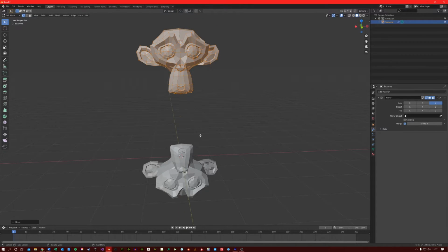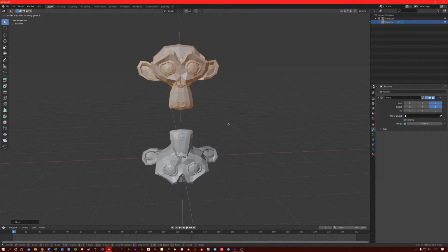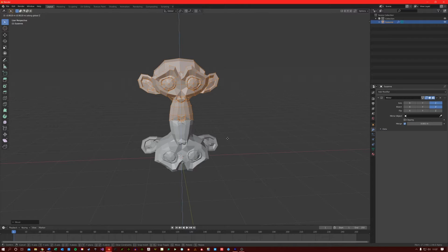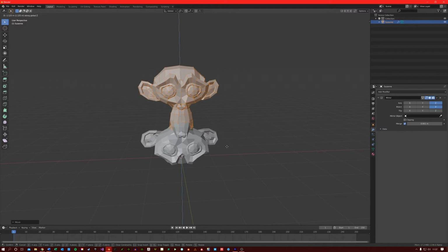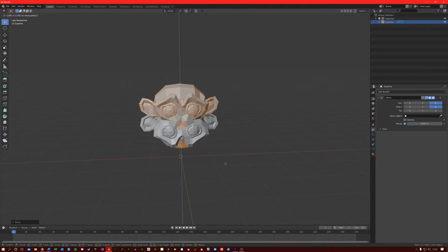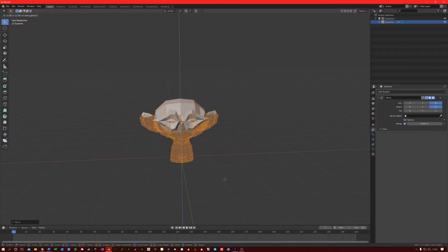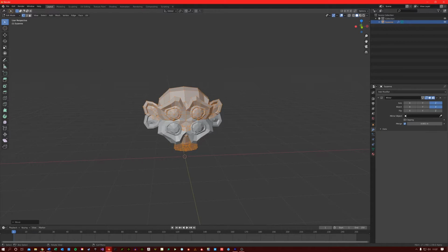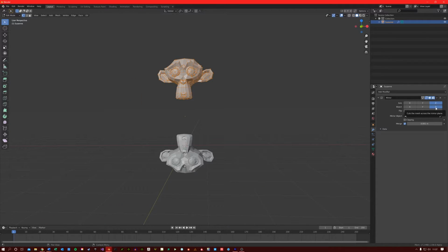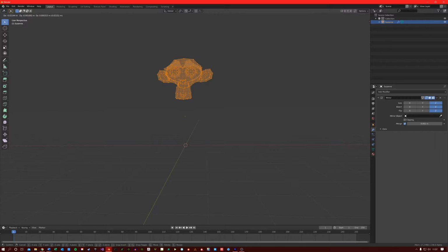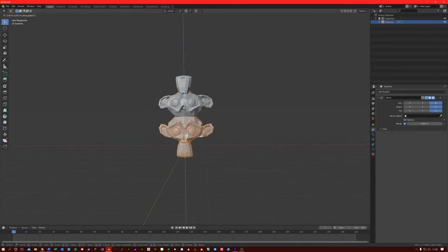However, if I now activate bisect for this z-axis here, you will see that the mirrored copy starts to get cut off as it passes the base object. The flip section works with the bisect tool and simply just flips it. So if I click Z on the flip section, you can see it's just the other way around.